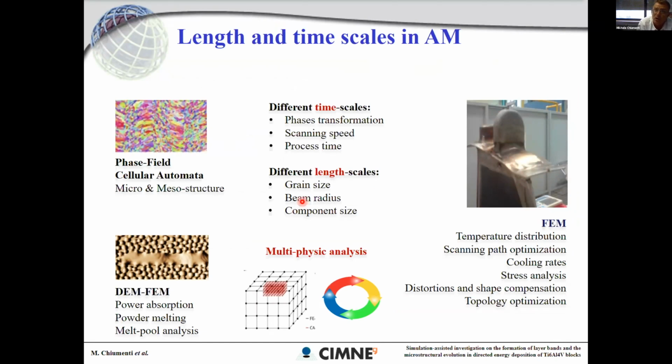So we are working at component scale, but it's also possible to work at the melt pool scale. It's also possible to work looking at the movement of the powder and its distribution, and the melting of this powder. And particularly, we had a nice work where we transformed the powder, defined as discrete elements, into finite elements once the melting happens.